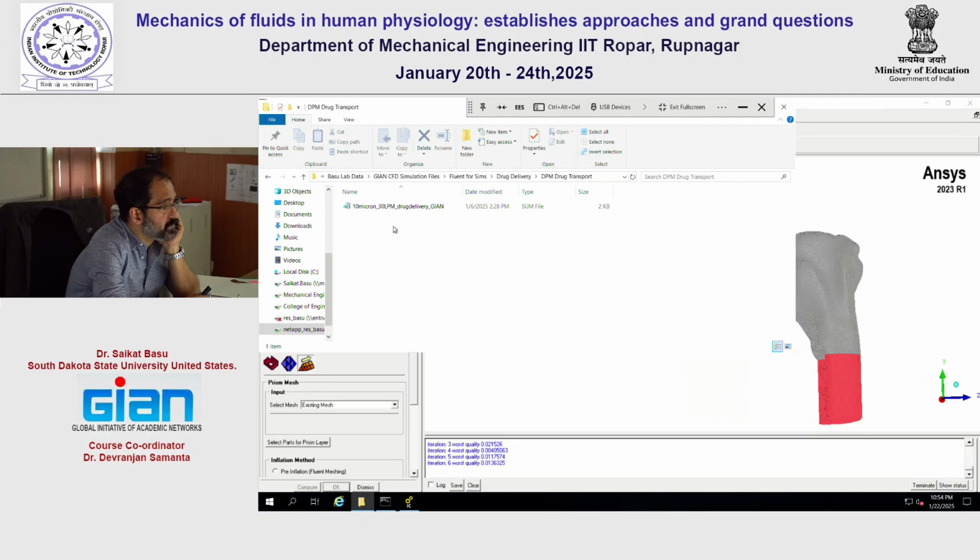Yeah. So you need to know the coordinates from where the particles are starting out from. Now, in terms of the pathogen transmission one, those coordinates are the centroids of the surface elements in the mesh. On the other hand, for the conical injection, because the spray is supposed to be inserted inside the airspace, you have to actually figure out what are the coordinates from where the particles are going to be ejecting out. And they are point particles, yeah.